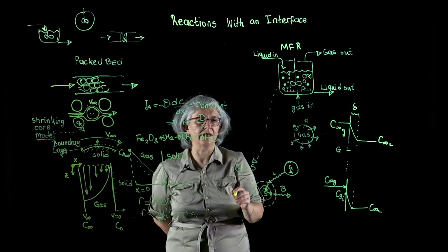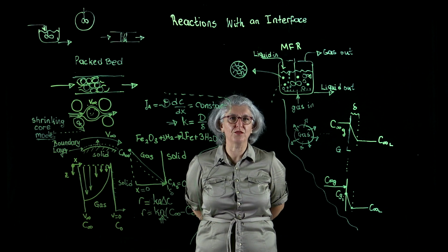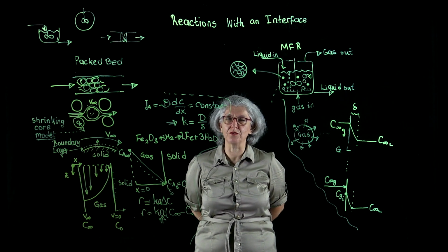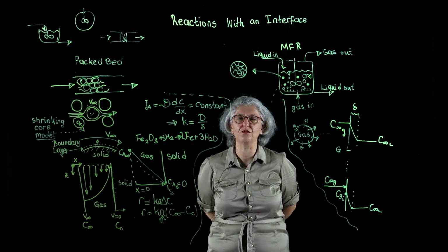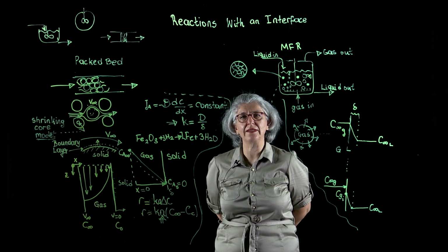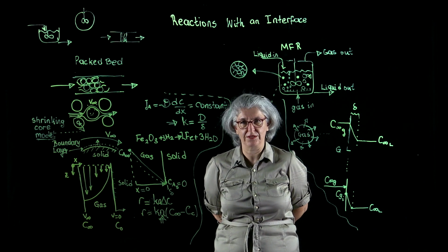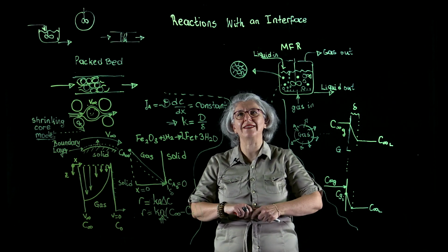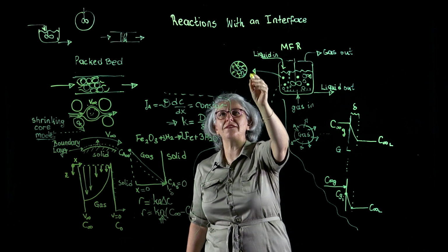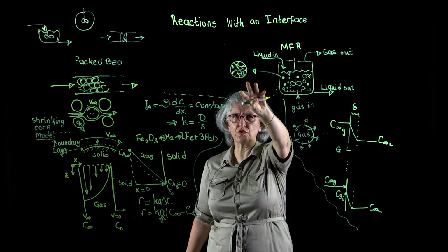And these type of reactions are not uncommon in the chemical process industry. The solid catalyst in this multiphase medium of gas, liquid, solid domain is a porous material. It has to be porous because we need to make sure that we have the maximum available number of active sites, and the only way that we can ensure this is to have a porous structure onto which we load the catalysts. Now, the porosity in that catalyst I represented through the tortuous paths, the lines. Now we are going to start our discussion from this spherical geometry with a tortuous geometry within itself.